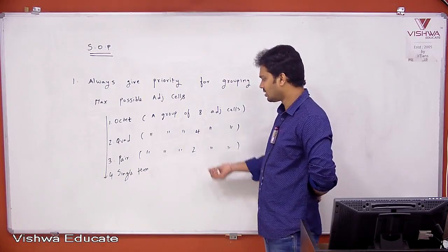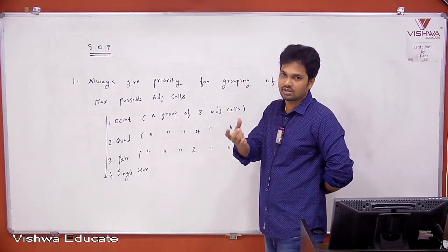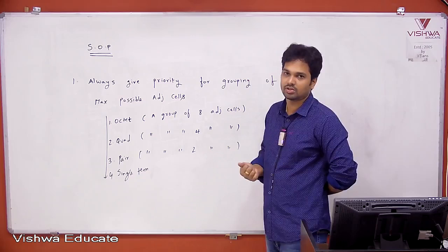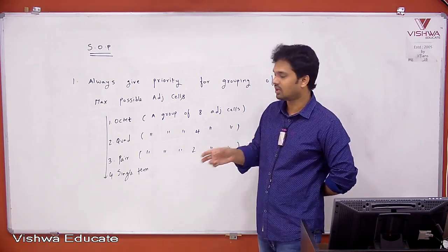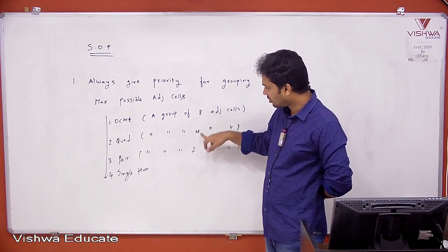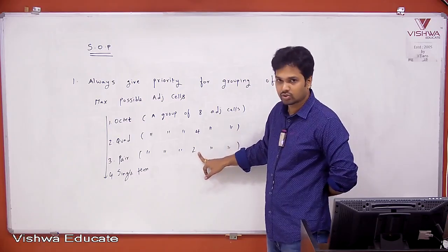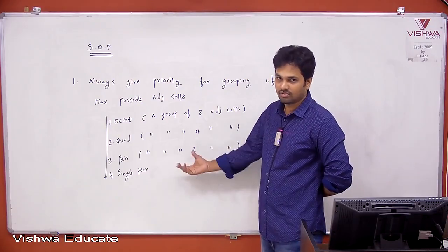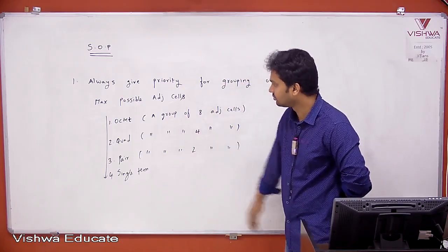You may have the doubt, sir, can I make 3 as a group? Generally, with respect to minimization in the K-map, I will show you, it is not possible. 3 should be taken as 2 pairs. 3 cells side by side, can I form them as a group, sir? These are the only groupings possible. If you have 3, we should take it as 2 pairs. I will show you when we discuss with the figure. Okay, so this is the priority. Please copy this.